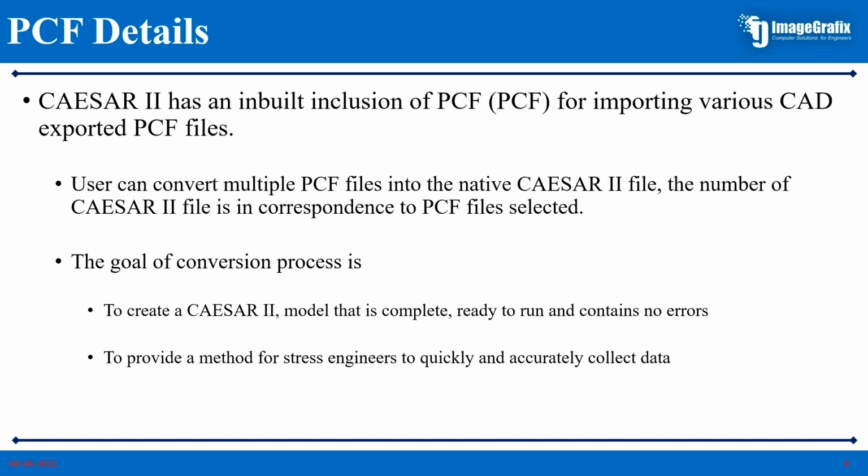All the mapping, everything can be done in this basic PCF import, but one thing: for each PCF file, you'll have one CAESAR file created. You can go for multiple PCF file importing, but for each PCF file which you import, you will get one individual CAESAR file created. Also, you don't have the option of controlling your node number sequences and all those things. Everything will be automatically selected by the software.